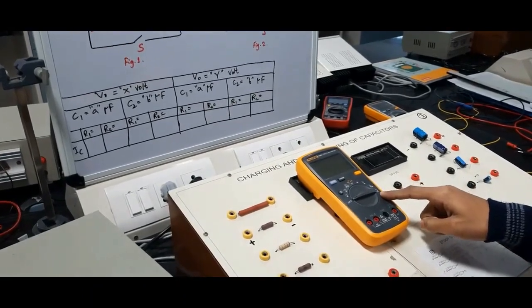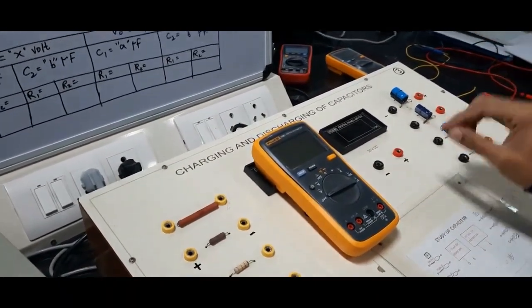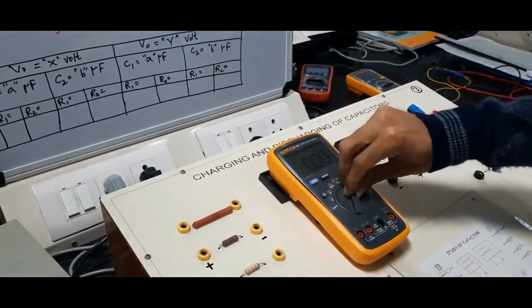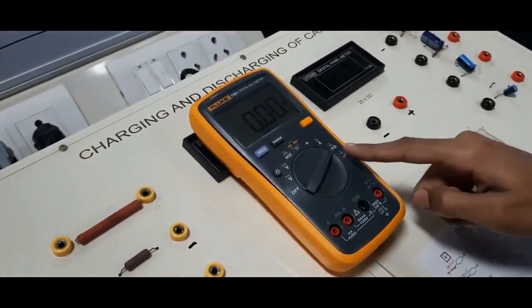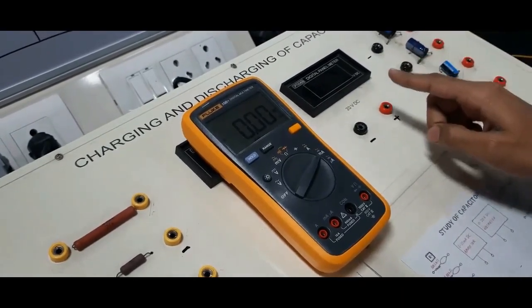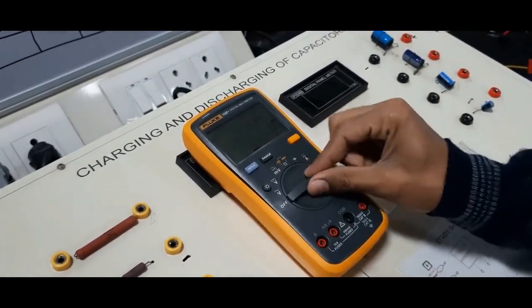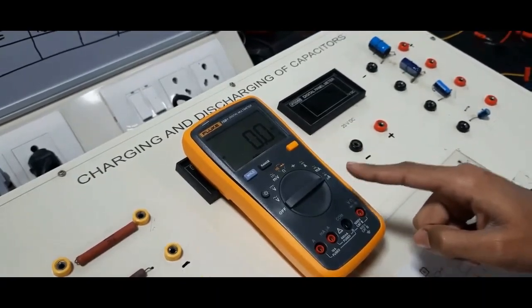So our plan is that first, when we connect the circuit and then charge this capacitor, we will first turn this cursor to the milliampere range, because it will show the reading in milliamperes, and when it shows a zero reading after the capacitor is fully charged, then I will change the cursor from milliampere to microampere to measure the leakage current, and from this leakage current you can easily calculate the leakage resistance.